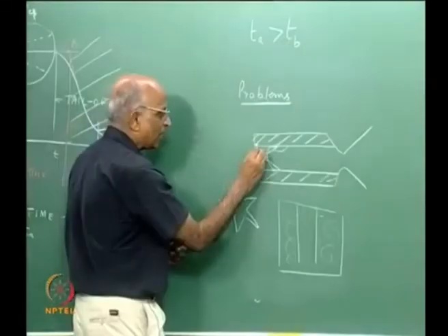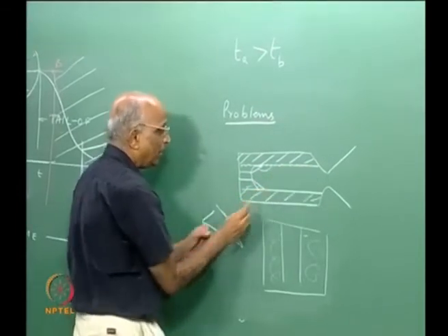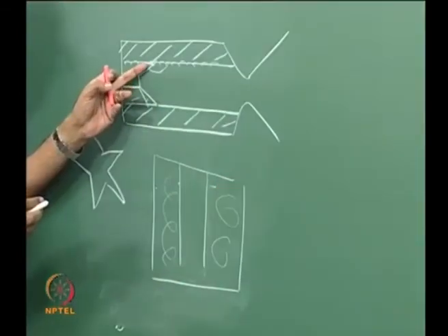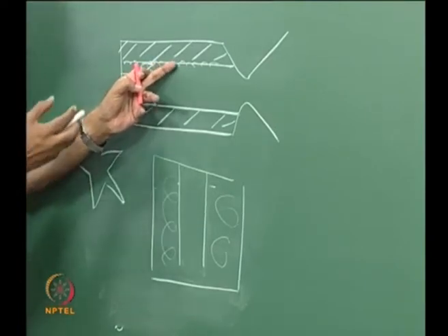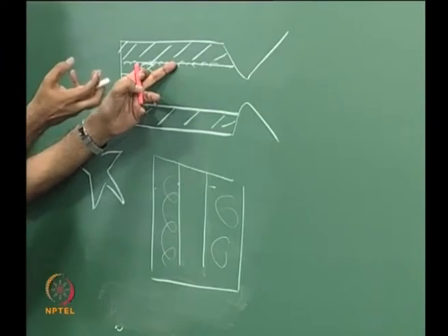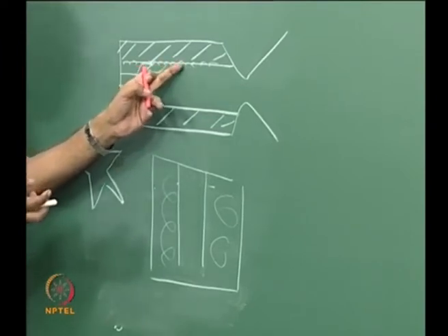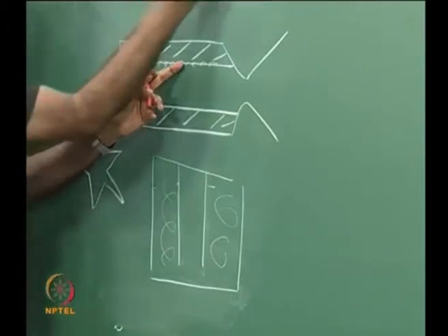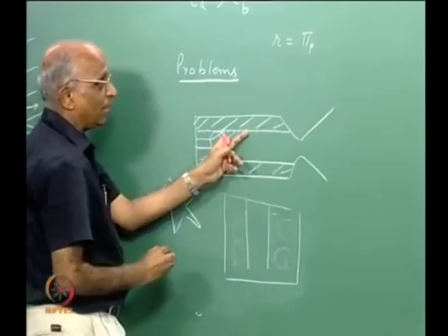Now if the surface of the grain is such that it is not easily ignitable, what happens? You are transferring energy, the grain gets heated, and as it continues to get heated, when it begins to burn, it starts burning at a higher temperature, and the value of R is now influenced by the temperature sensitivity factor.